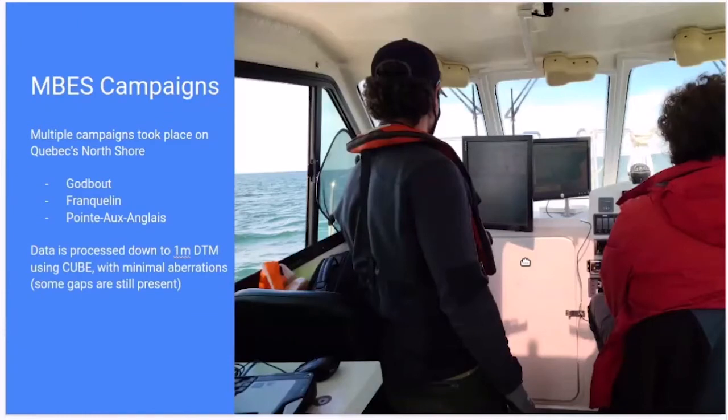To this end, CIDCO has undergone several MBES campaigns, notably on Quebec's North Shore. I'm going to be talking about three of them today: Golbou, Franklin, and Pointe-aux-Anglais. The data is basically your standard multi-beam echosounder system data. It's processed down to a 1 meter DTM using Cube and with minimal aberrations.